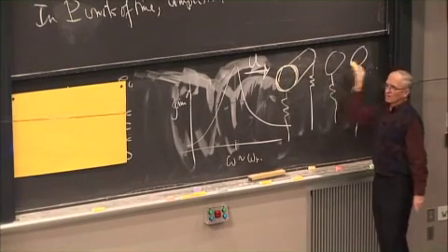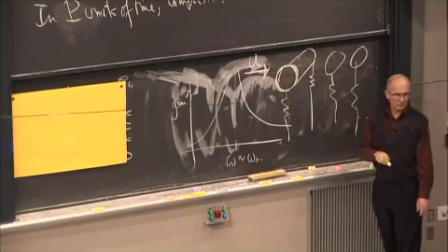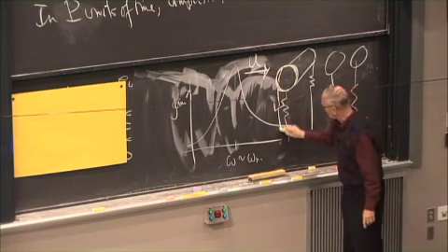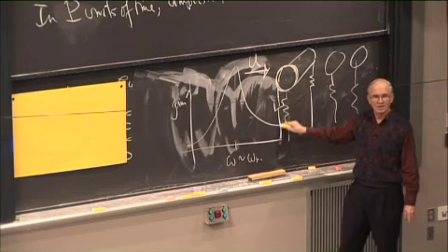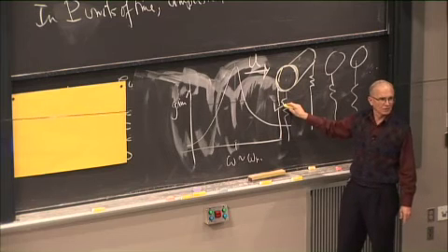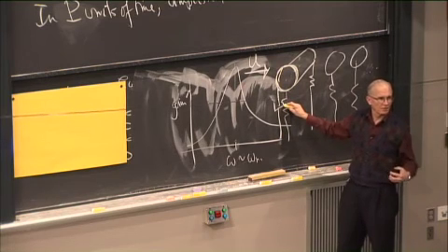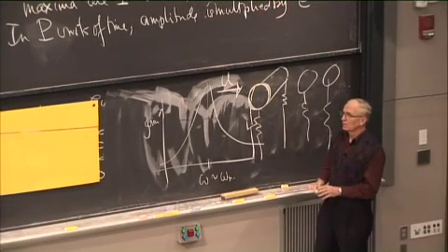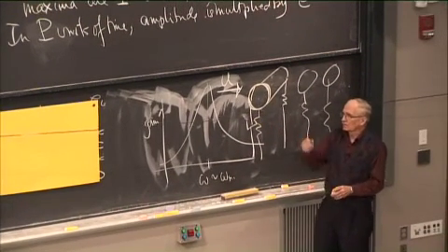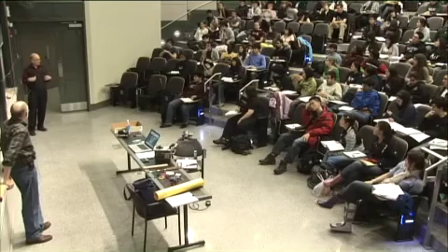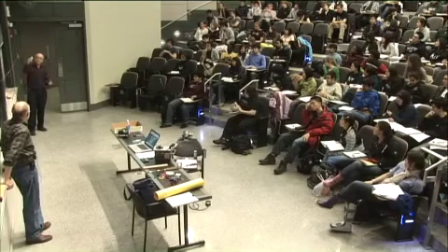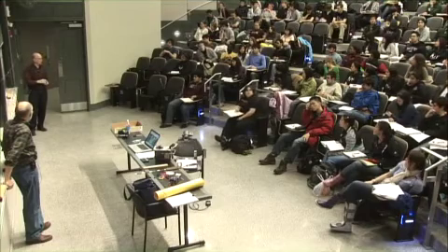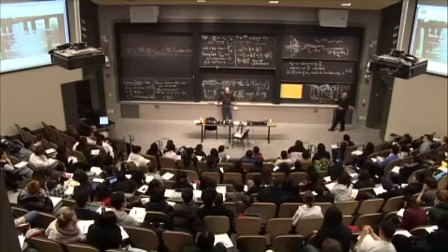And they're excited by these vortices coming off the cylinder. And instead of a dash pot, instead of just an ordinary damper, the damper is the generator that's hooked to it. Generator sucks power out of it and acts like a damper in the system. Instead of just heating up the damper, it's doing something better. It's actually sending electricity down the wires. Okay, but it's taking energy out of the system. The equation of motion is exactly the same. It's that same oscillator equation that we started with today. So we're going to show you a movie of this thing in action.